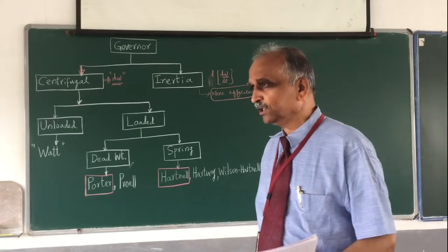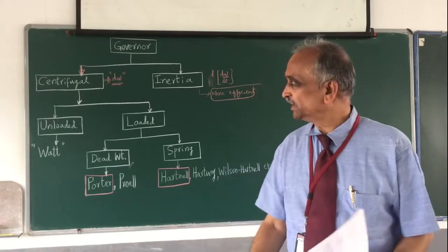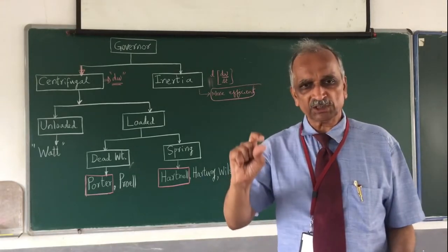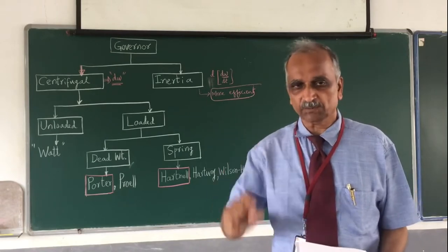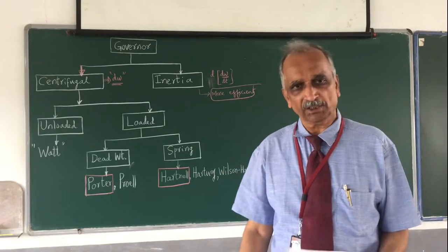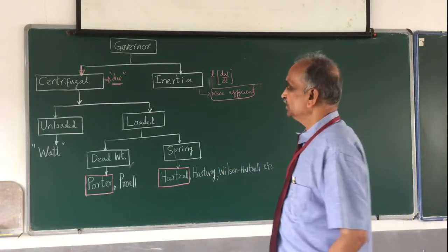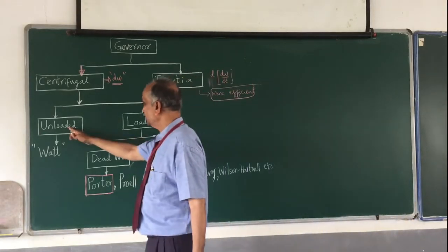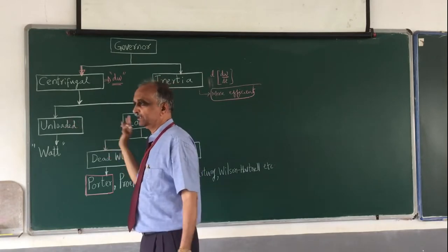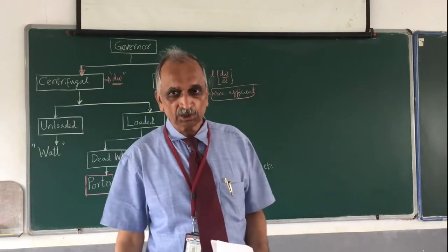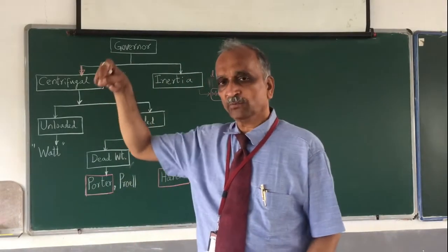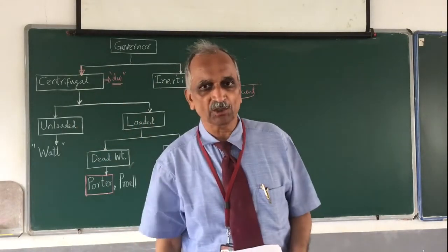For very effective functioning of the governor, if the sleeve displacement is made larger, then the governor will function better. Now, unloaded and loaded governor. Load means force.